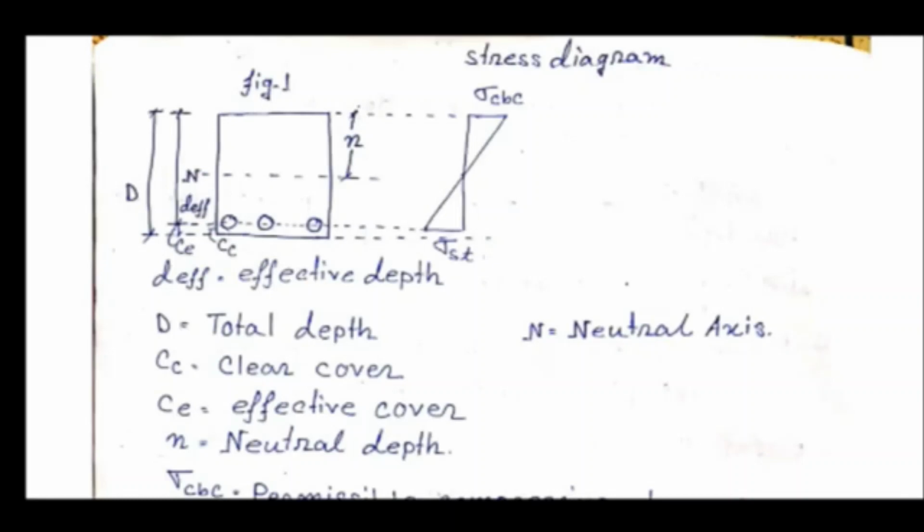You can see 3 circles in lower portion. These circles are cross section of reinforcement bar. As I told earlier, tension is completely taken by steel reinforcement bar as per assumption. That's why in tension zone reinforcement is necessary. In upper portion also reinforcement is given, but mainly to make the mesh.